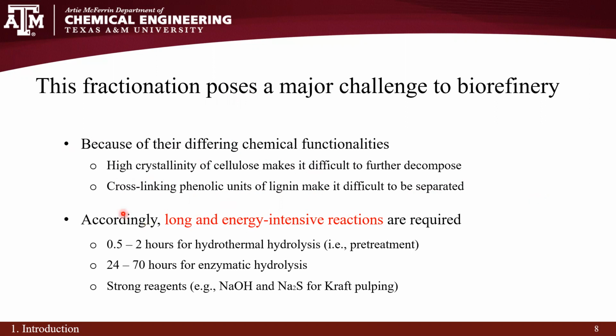For example, when there is a large amount of residual lignin on the pulp, then half to 2 hours of hydrothermal hydrolysis and 24 to 70 hours for enzymatic hydrolysis are required for the further processes. And also, strong reagents such as sodium hydroxide and sodium sulfide are needed for the subsequent processes.